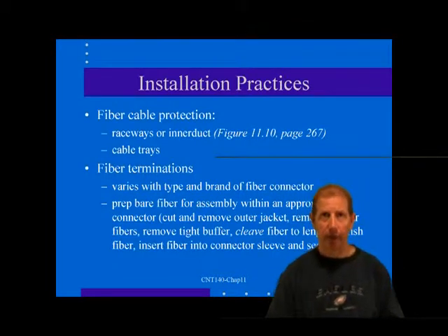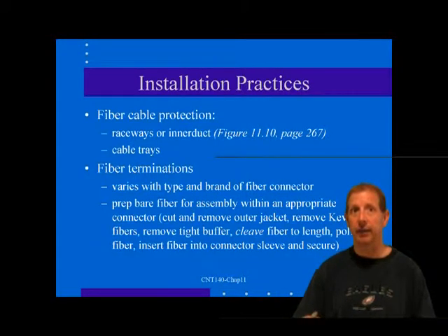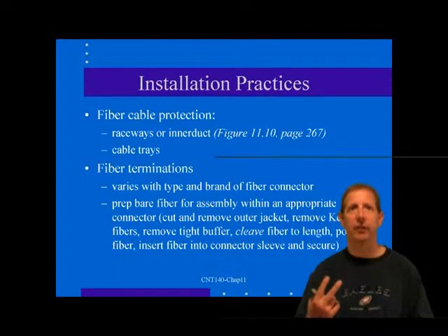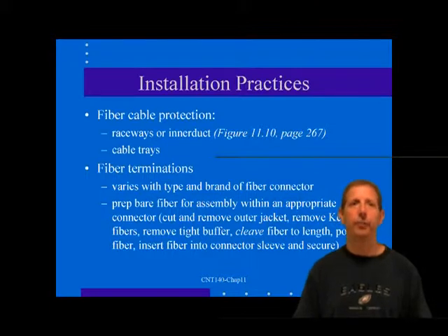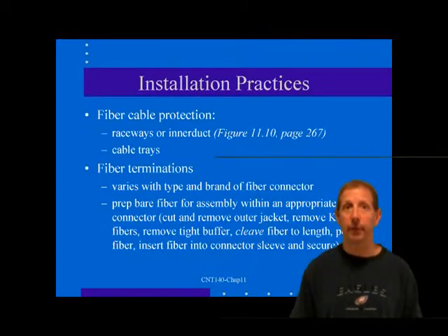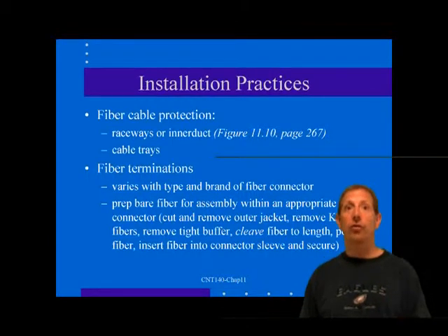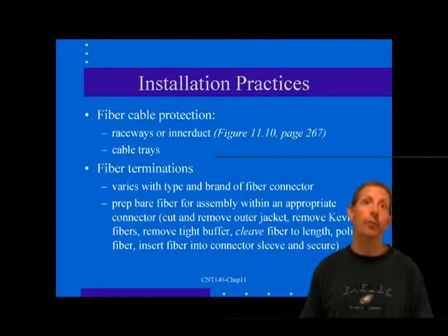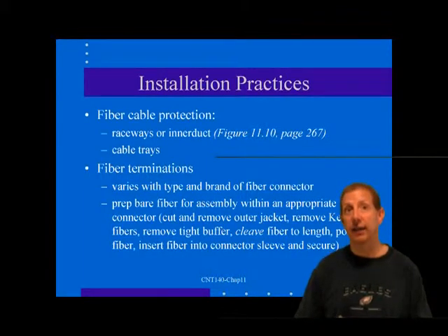If we look at fiber cable protection, the degree of physical protection the fiber link requires depends on 2 factors: construction of the fiber cable and location of the cable run. In a fiber distribution panel, very little is needed in the way of physical protection for the fibers. What is needed is some type of fiber management and fiber storage. On the other hand, fibers that are used for horizontal or backbone runs do need more protection.